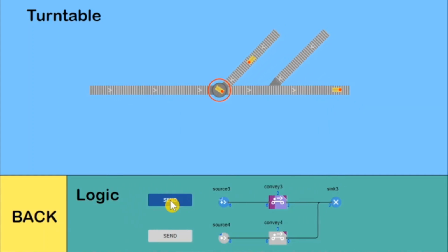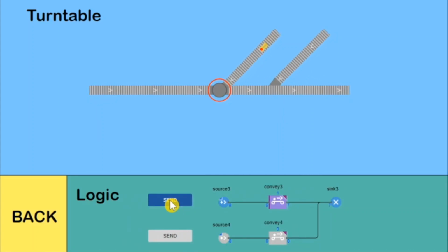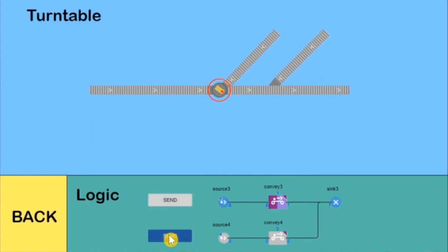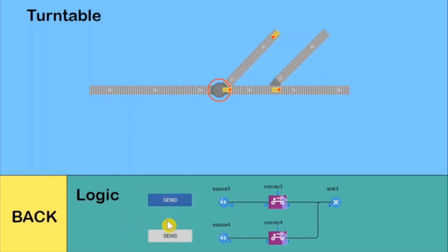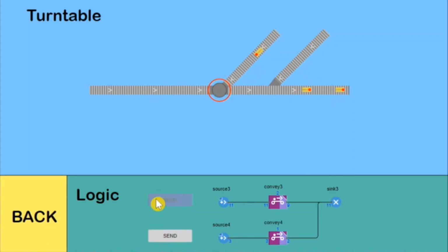Turntable has its own transportation speed, and the time required to switch to another conveyor can be defined by setting the rotation speed of the turntable. The difference between conveyor spur and turntable is that conveyor spur will instantly change the direction of the agent, whereas the turntable will take account of the rotational time.